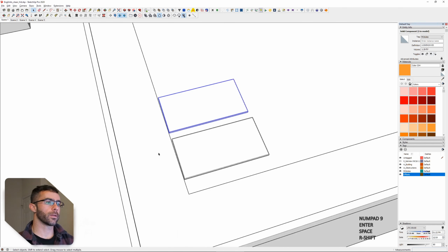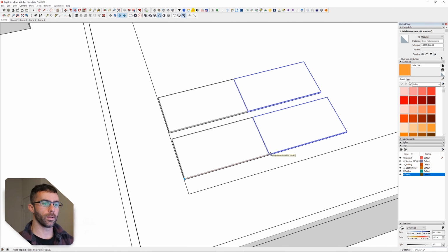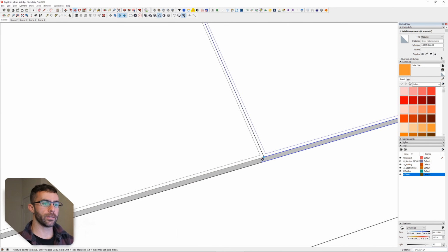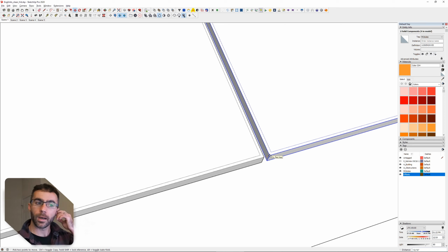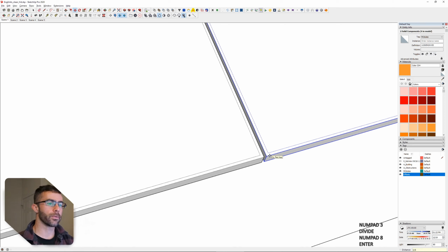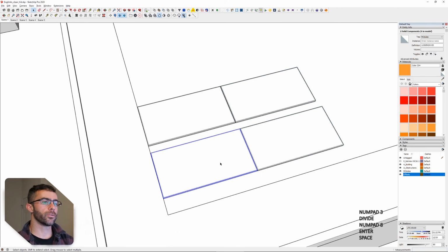And then the other thing, sorry, I'm checking my notes, is we want to add a little bit of space between the modules. So if you go in edge to edge, typically it's about 3/8 of an inch to an inch space between for the hardware. I'm going to go with 3/8. So I just type in 3/8. Now we have a 2x2 array.